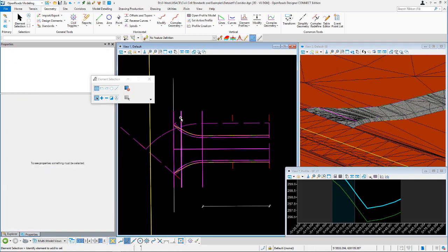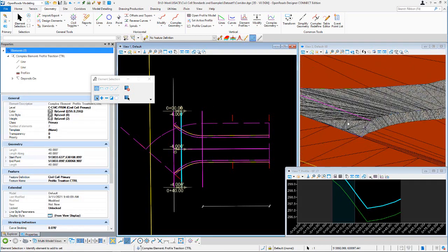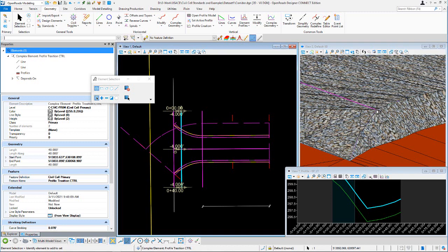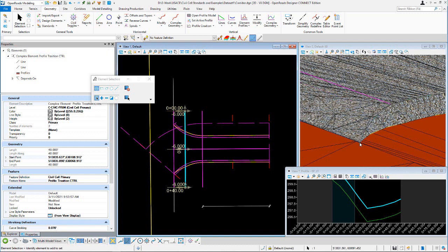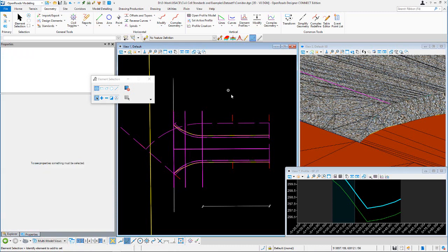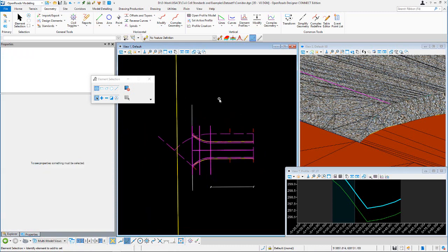You can adjust that, right? So if you want to move, basically we get 1 foot here. It's really just a transition down to the ground there, but you can adjust that. So if we change that to -6, that's going to back up, give me a little more transition from 0 gravel to 1 foot of gravel back here. All right, so as far as the cell, that's pretty much it.